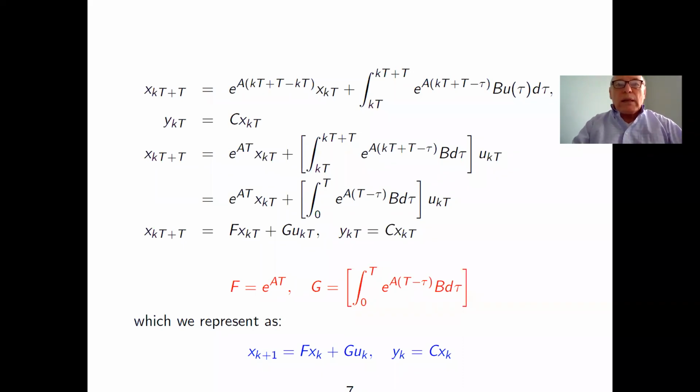Using that formula, we can easily simplify all these expressions so that we can obtain a map that relates the current state and the given control input to the next state. And by doing that, we just simply simplify the exponents of the exponential matrix, and we obtain, by means of a simple change of variables in the integration operation depicted here, the sum of two terms.